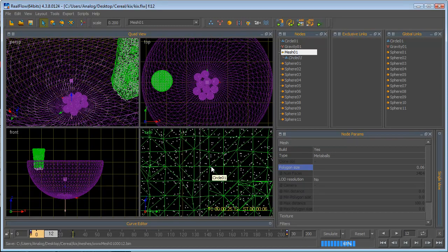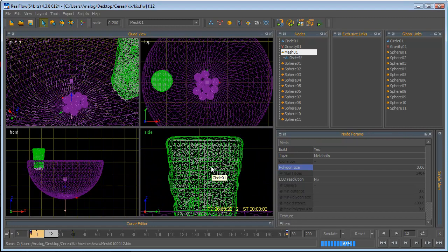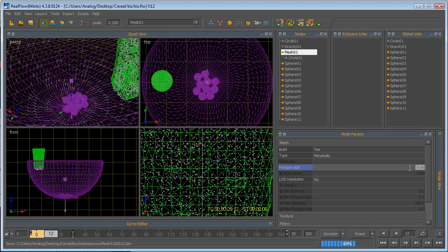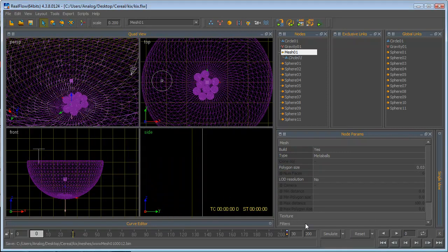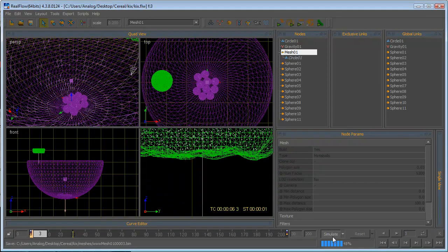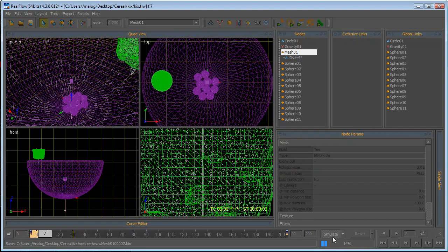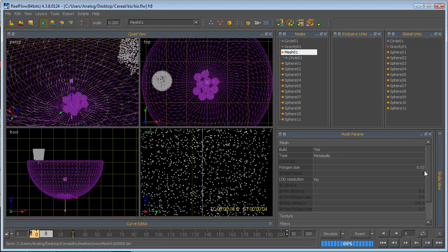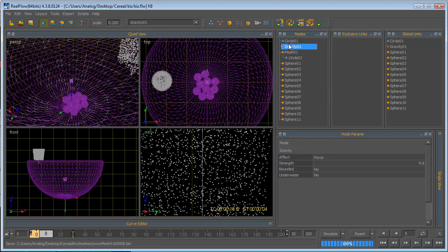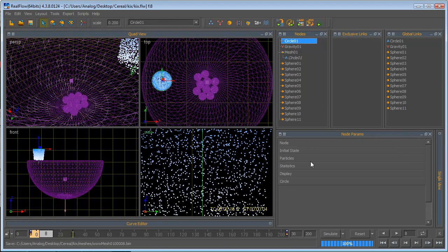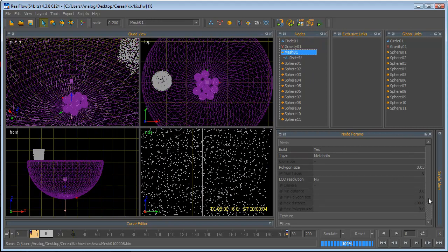And what do you guys think? Do you guys think 0.06 is good? I think that we could, I'm going to go down a little bit. I'll change it to 0.03. Half the size. Reset. And you can tell the difference on the mesh. Okay. So like higher the resolution, the smaller the mesh you're going to want to have. Okay. So we have a resolution of 5 on our particles. And also depends on the size of the scene too.